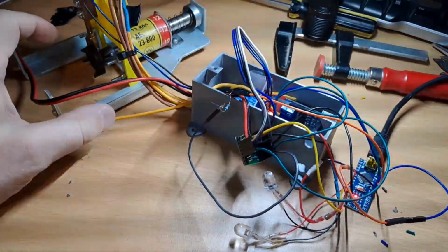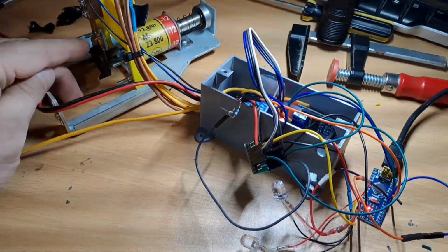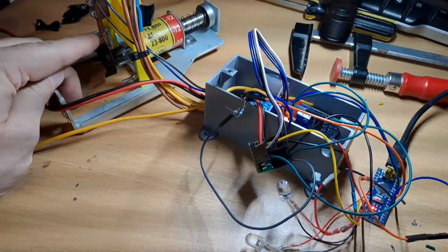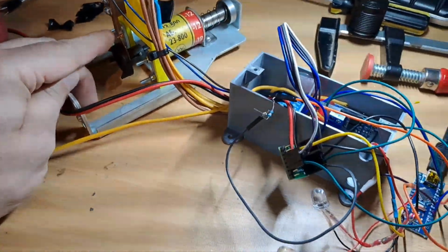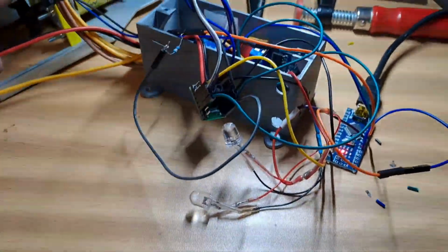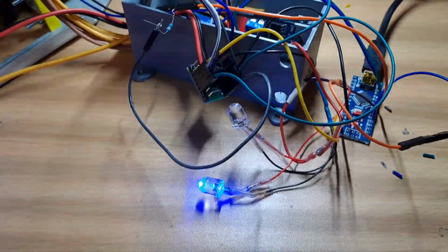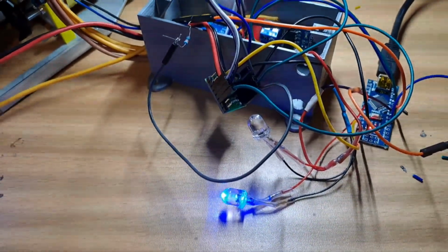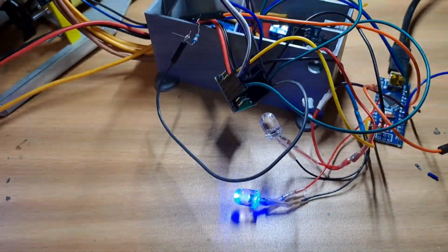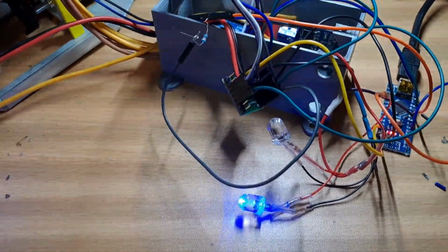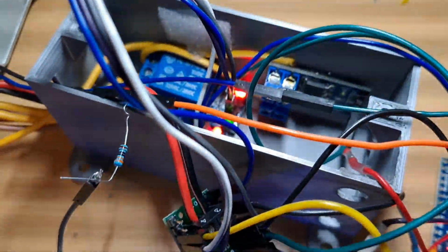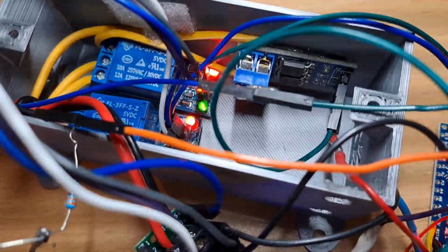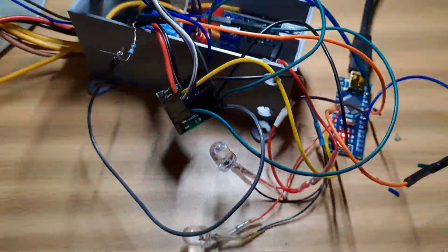So you got the VUK over here with the ball cup and the fork switch that I've mounted here. I 3D printed a little part. And when the fork switch closes, then here you got an Arduino. This blue LED illuminates. Now there's a ball sitting here. Now the game should kick the ball out after it awards a snake run. But if it doesn't, like there's a ball sitting there that does not get kicked out, after 12 seconds, these relays here that you just maybe saw, the green lights illuminated. I'll start the whole process over again.